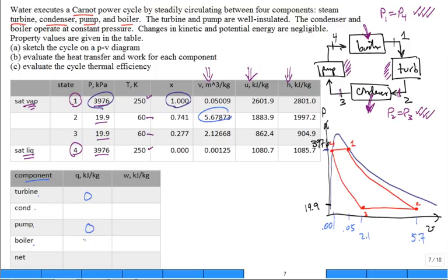But now let's analyze the turbine and let's introduce a control volume around that turbine. We know that the work is out of the turbine, that's a lowercase wT. The rate of change of energy in the control volume with respect to time is equal to the rate at which it's flowing in with heat minus the shaft power out, plus it flows in with mass, bringing with it its enthalpy, neglect changes in kinetic and potential energy, minus going out the enthalpy.